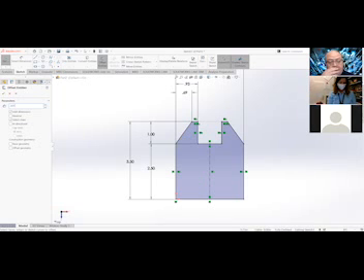Now, SOLIDWORKS is kind of nice, and you can put in the decimal, or you can type in 5/8. It does both just fine. It converts very well. In fact, in this little box you can even put in a plus and another value, a minus, a divide, and it's a calculator. It does everything for you. But we just need 5/8 right now.